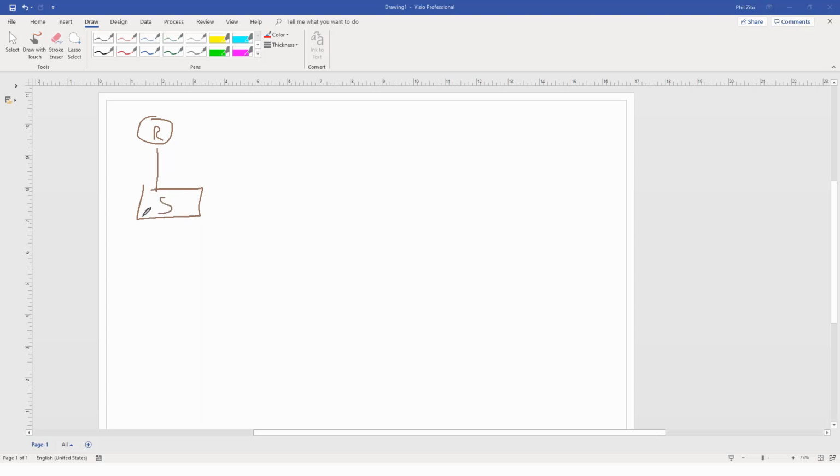And each switch is going to have a port, and we're going to coordinate with IT and find out what ports they want us to use. And then on our drawing, we are going to have a table, and it will have the device, right? It'll have the IP address, it'll have the port, and it will have the pattern. Although the pattern should be able to be inferred by the electrical contractor who's installing all of this, but that's what we're going to do. Device, IP, port, pattern. That's going to be like a bill of materials, but it's actually a network list.